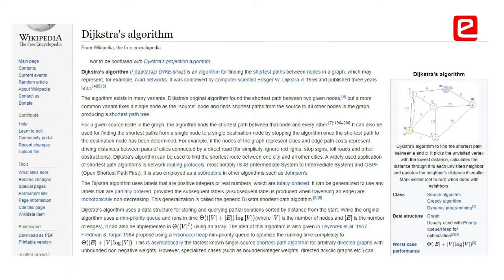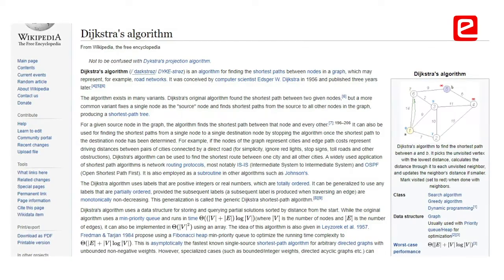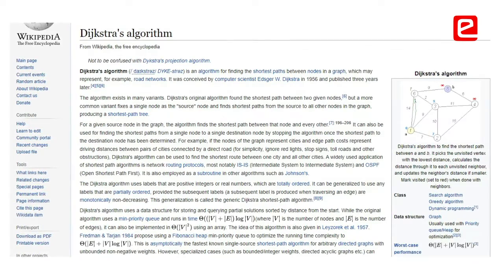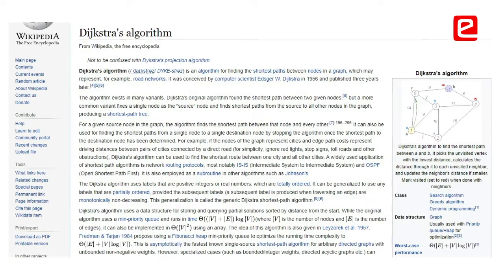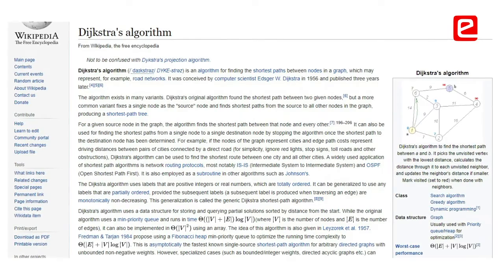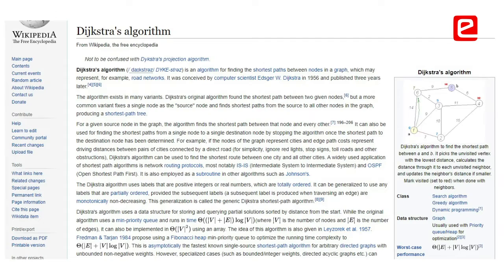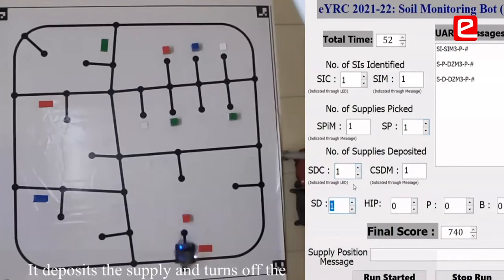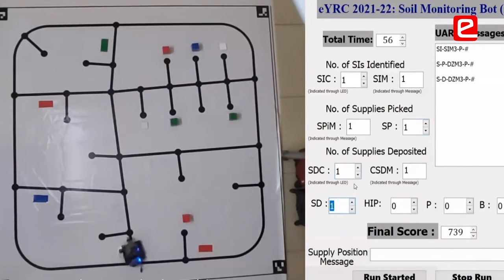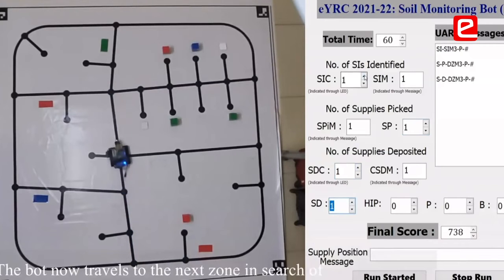If we were to do it in traditional programming languages, we would iterate through an array, and the Dijkstra solver would find the minimum available path in this array. So it had to iterate n times. If there are 26 nodes, it had to iterate 26 times, and it gave you the shortest path. I eliminated that altogether by using combinational logic.